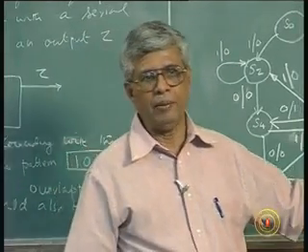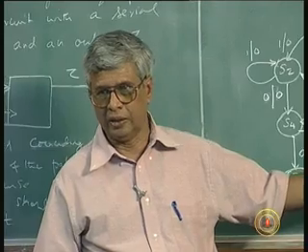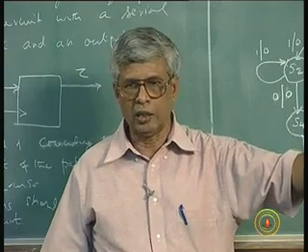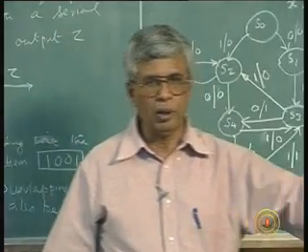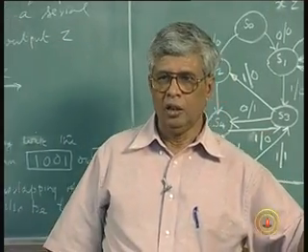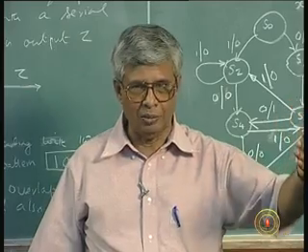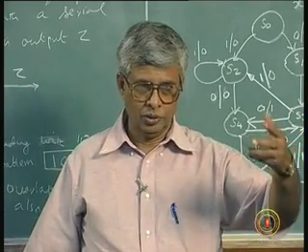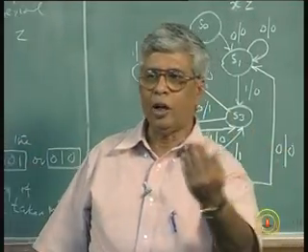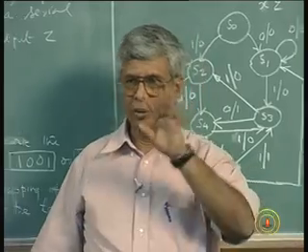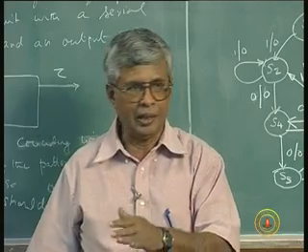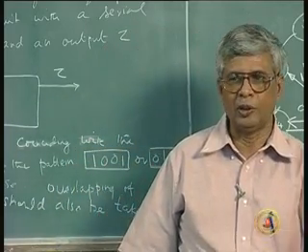If there is time left, we will probably do that part with a couple of examples. I can show you how a state graph with more states than required can be reduced to a state graph with a minimum number of states. There is a technique for that. Even if it were not available, I would rather go with a conservative state graph which will take care of all my possibilities, than draw a simpler graph and ignore some of them. Of these two options, I will any day prefer the one with more states, where I can solve the problem to the entire specifications.